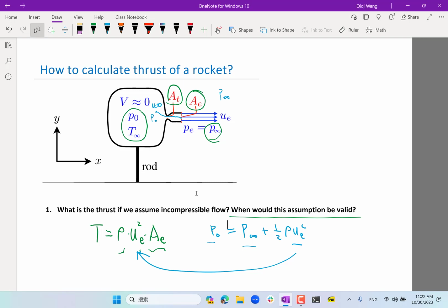So that's useful for figuring out whether the flow would actually be subsonic or not. But in this case, if the whole flow is subsonic, it's not that useful to calculate a ratio of an area versus the minimum area where the flow is actually at Mach 1. So there is something else that can be used to calculate the Mach number at someplace else.